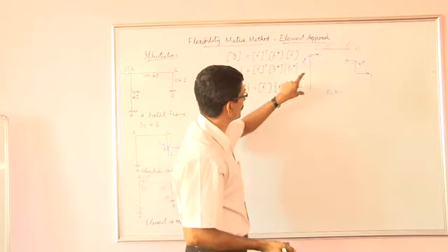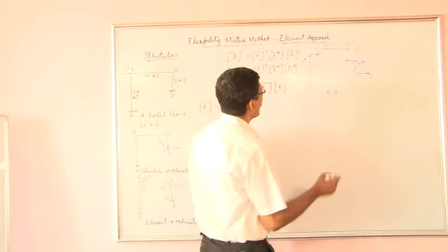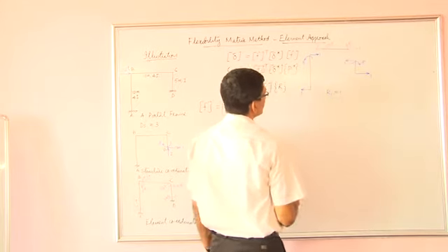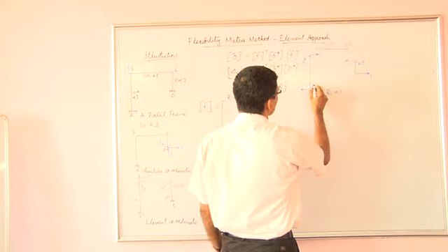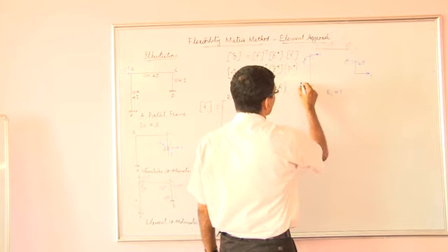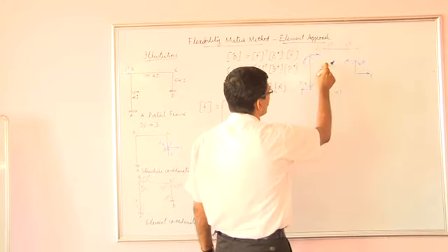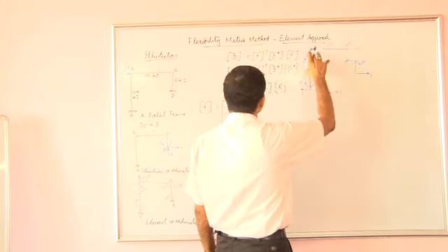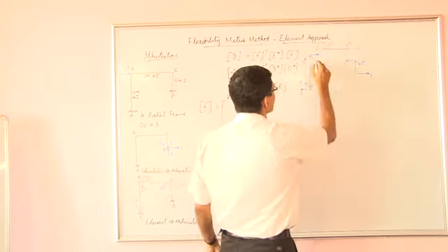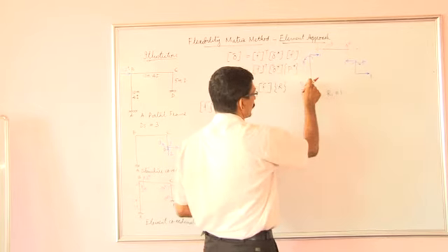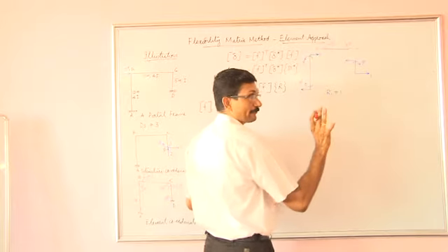Now further, for equilibrium of this column we have to apply a force 1 over here for force equilibrium and a moment equal to 5 to oppose or to equilibrate this moment. Now the moment produced by these two forces would be 1 into 10, that is clockwise. So to equilibrate that, we require an anticlockwise moment equal to 10. So that moment at this joint would be anticlockwise 5.